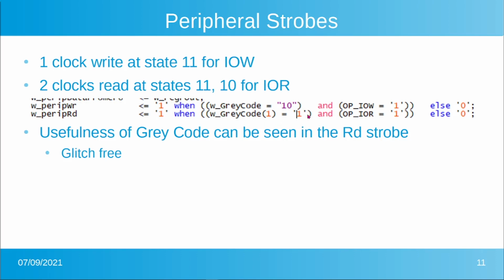If we're decoding a counter and you want to say, hey, is this counter that? Unless the output of the comparer is registered in some way, you will get glitches and things can go bad. So this is just something you learn if you've been playing with this stuff for a while, but it's worth reading up on gray codes, and I'm sure there are better introductions to why they're useful for making glitch-free designs, but this is what you want to do.